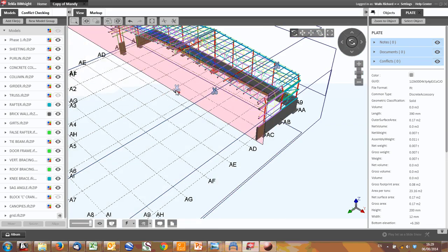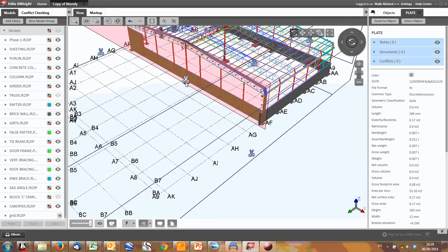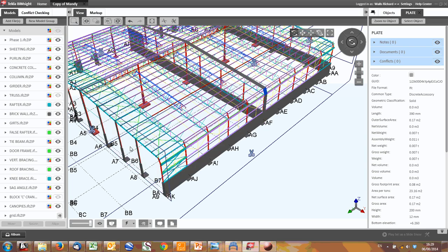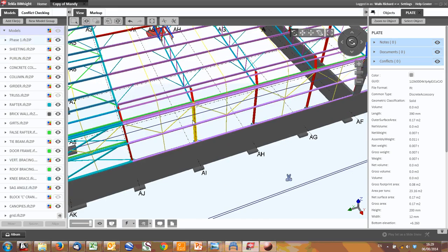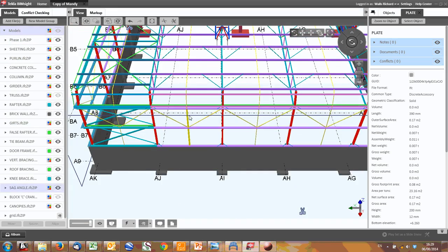And let's go back. And the number of bays, if I come through here and pull this building out, the number of bays is governed a bit by selection. First, and by bay I mean the distance from column to column. Normally this is between sort of 5 and 7.5 meters.